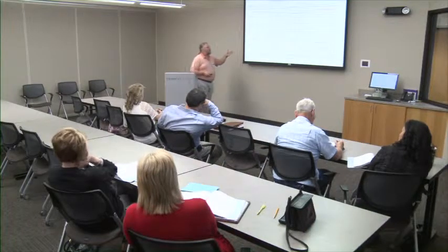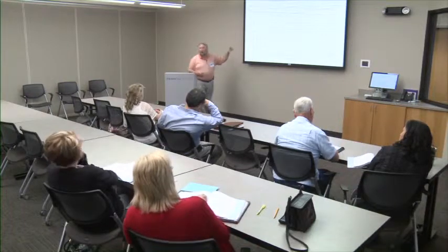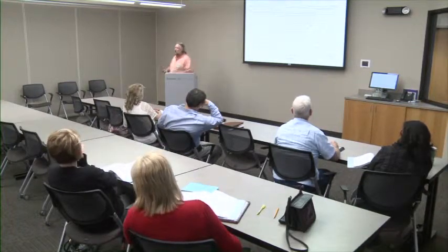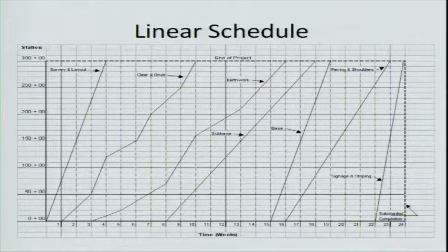And then this is a linear schedule, and mostly they're used for highway work. And since this is an ODOT class, this is probably the best set of schedule that you can work, because you can lay out different things, because in most ODOT projects, more than one thing is going on at the same time. You know, we're putting down sub-base as we're grading earthwork farther down the line, or we're building bridges as we're building subgrades. So we can look at it in a linear progression of how we need to get to where we want to go.